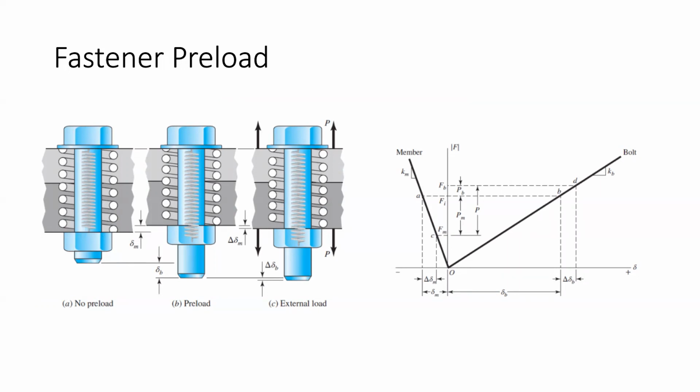You usually want really high torques to prevent your system from loosening, but also sometimes you want to generate really specific amounts of axial load. The most common case is a bearing configuration. So in general, when you're designing and selecting fasteners, you should recognize these two things: I want to produce some amount of axial load, but at the same time there are considerations of the joint strength and how stiff the joint is. That all goes into play when you choose the fastener. Those are the main things I wanted to cover today.